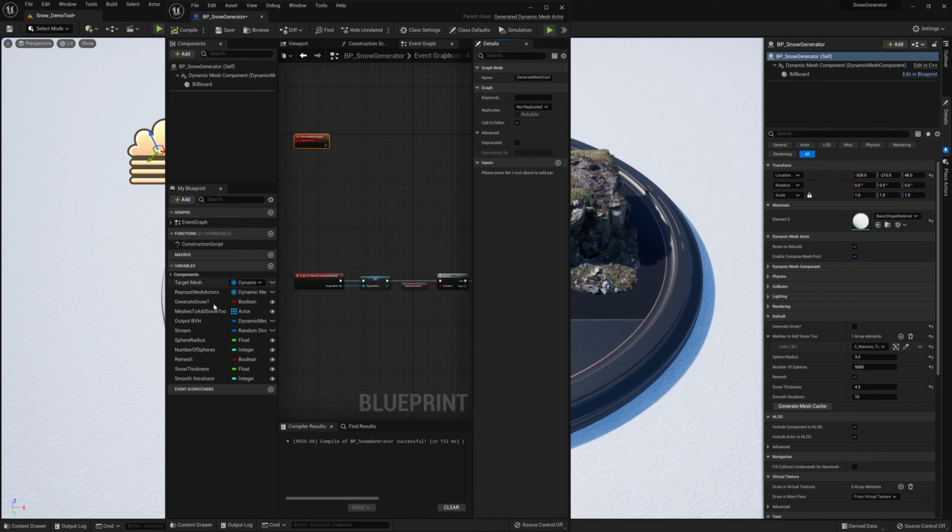You can obviously put these into groups, which will move some of them back up, but this custom event I don't think can be given a group, so it means it always sits in this default tab. In this particular geometry script blueprint that you use to get the On Rebuild Generated Mesh node, it seems to not order them in the same way as some other blueprints do. So anyway, if you've lost your variables, then check where the default category is, and then you'll be able to find it.